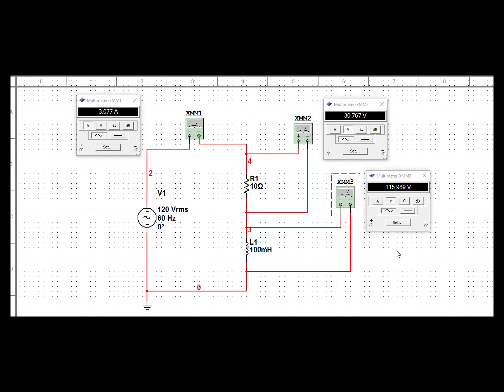But first of all, just so you remember, this is something we have to really start to get our head around. When you're working with AC volts and reactance in a circuit, these two voltages are not in phase anymore. The resistor voltage at 0 degrees and the inductor voltage as an imaginary value of plus j create a voltage triangle. And the voltage triangle is what proves Kirchhoff's voltage law here.